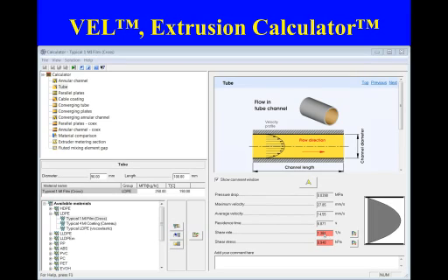and our shear rate is 1.4. Now, this is one of the unique features of the virtual extrusion laboratory, and I don't think any other analysis software for extrusion has anything like this. We have checking parameters for each polymer group, and the checking parameters are used within the modules to highlight potential conditions where there are problems or potential problems in the system.